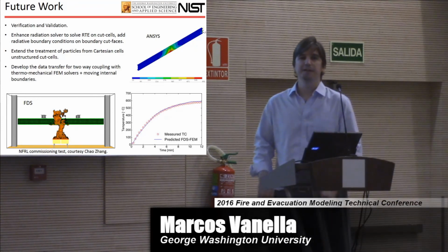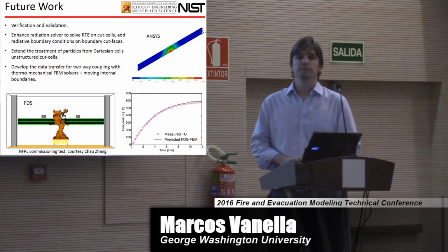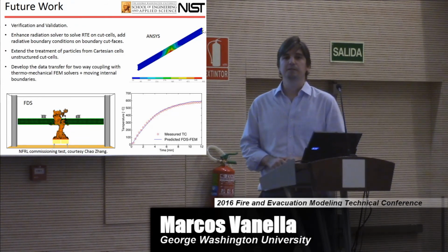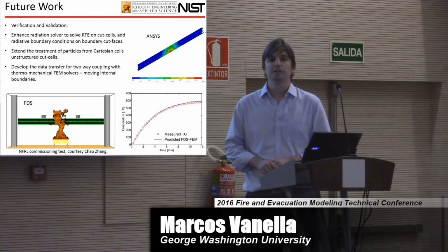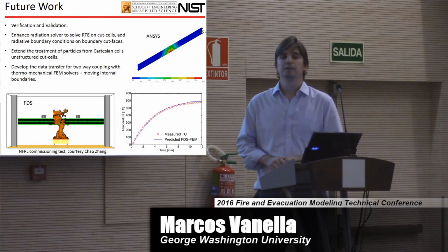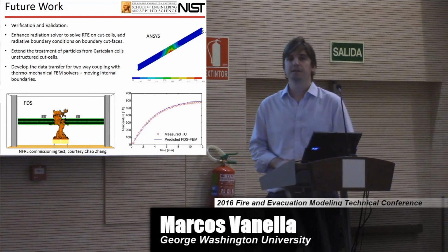Hello, Wojciech. That's very impressive work. I'm wondering, because when you implement the immersed boundary layer around an object, a bluff body, then this layer is also a kind of a wall layer for the turbulence model. How do you plan on incorporating the LES model with this area? Yes. Thank you.